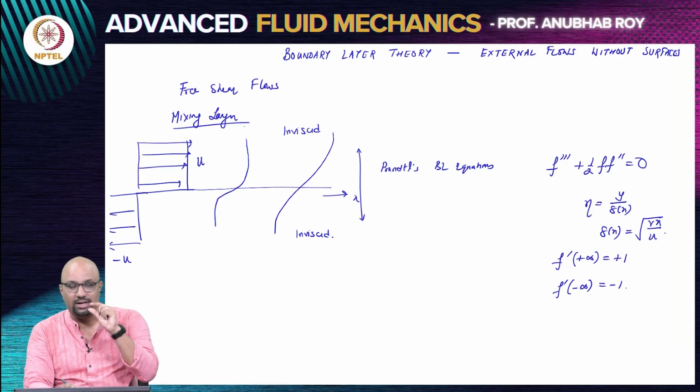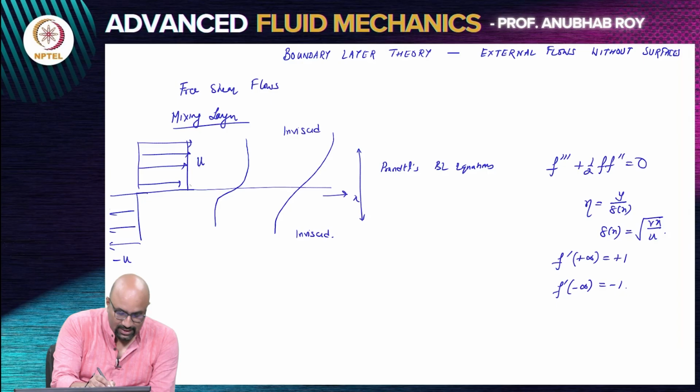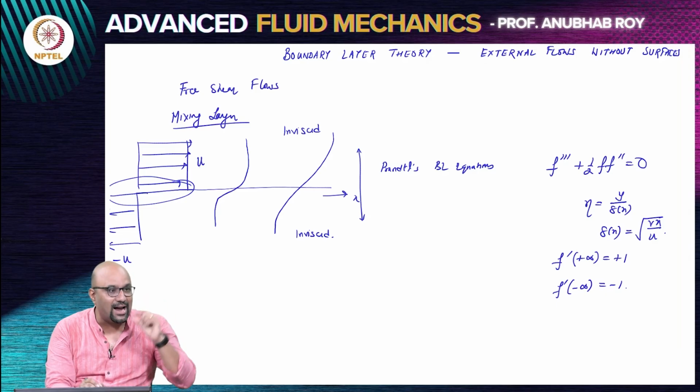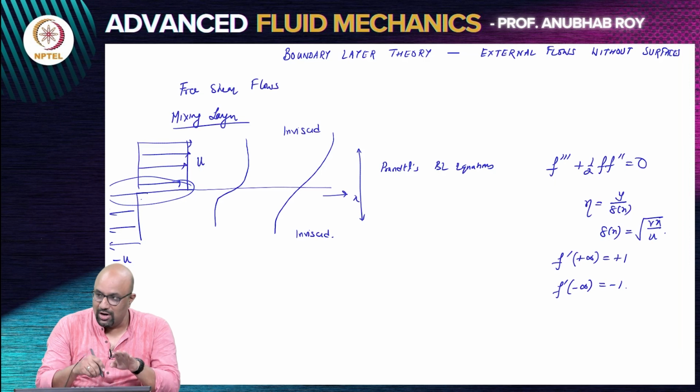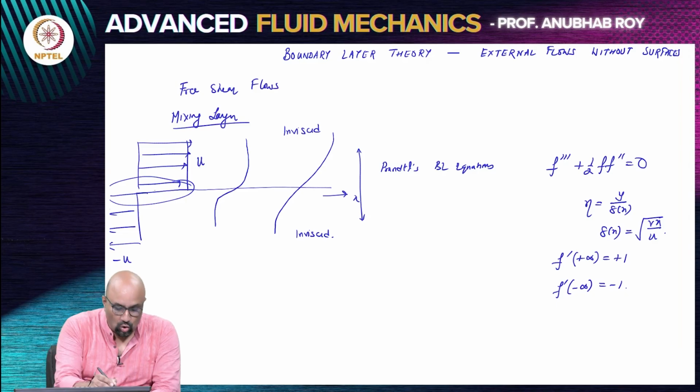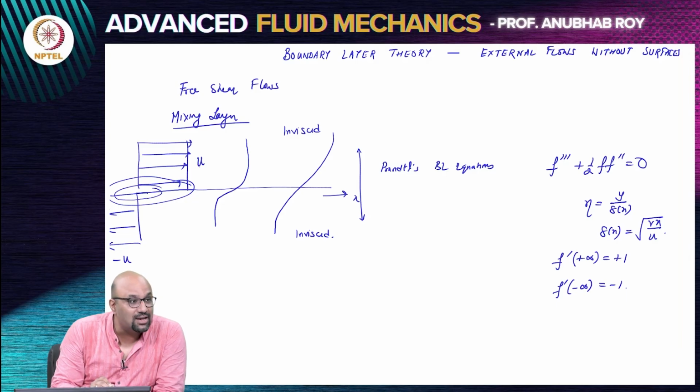Because there is a strong region of shear in this problem, this is a region where if you compute the velocity gradient it is infinite to begin with. So, at x equals 0, the two streams have 0 velocity gradient everywhere other than exactly at y equals 0. So, when you have this strong shear, howsoever large inertial effects may be or howsoever small viscous effects may be, even for negligible viscosity, you will not be able to sustain this infinite or very large velocity gradient.